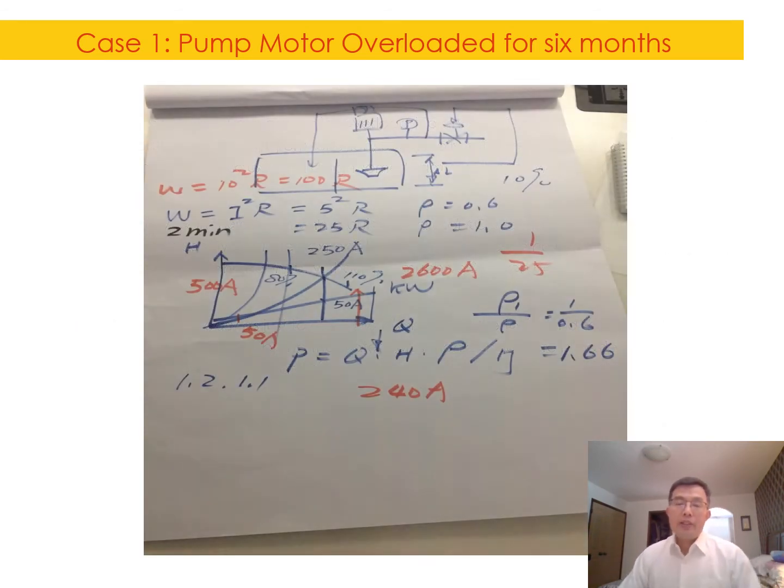If we look at here, we give a simple drawing here. This one is a motor, and here is a pump, and we're pumping this one to outside, right? So in this case, what we use here is a pump performance curve, and one of the equations here is the power of the motor equals Q times H, where Q means flow rate, H means the head, times lambda, the density,